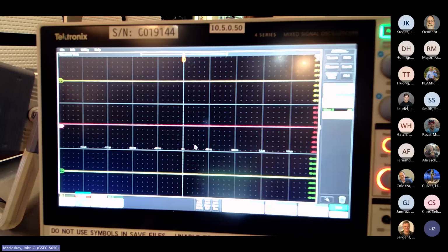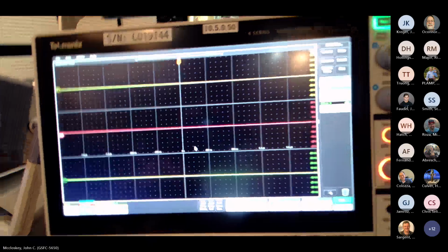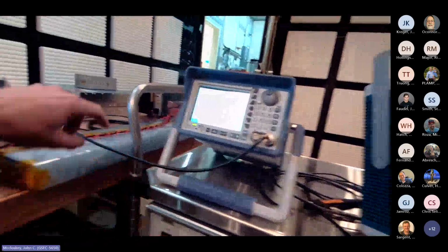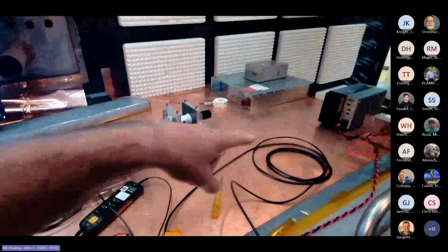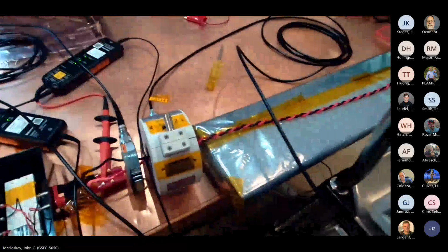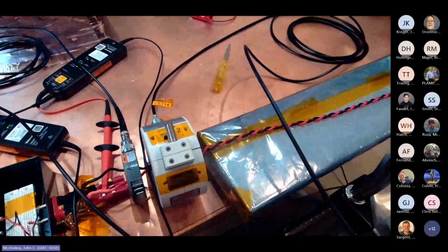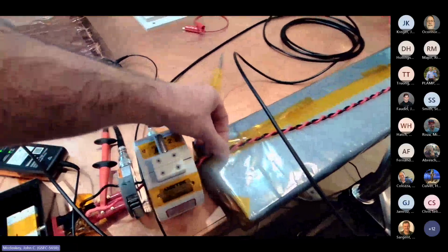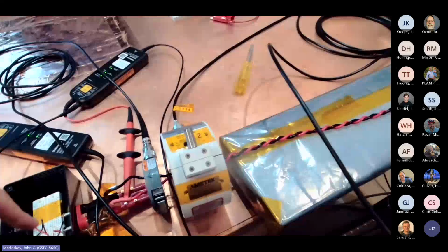All right. So, second and third set of eyes. We got our signal generator going into our injection probe, through this cable here. It's the same cable we've been using, connected to our injection probe, clamped around the power cable to our EUT.